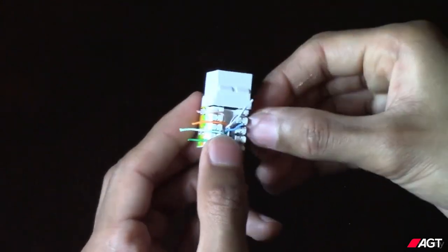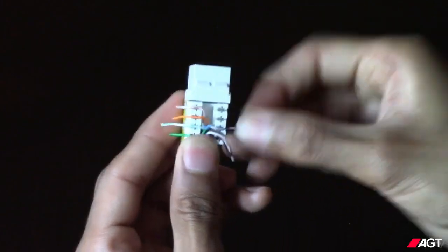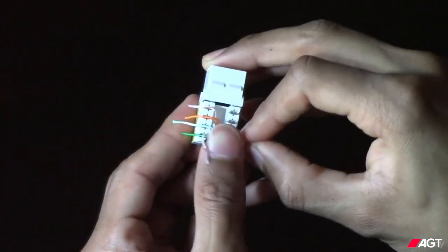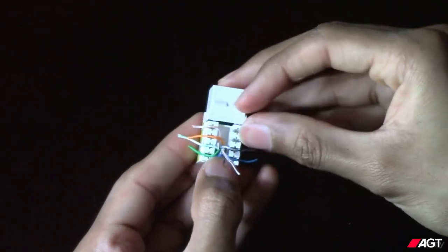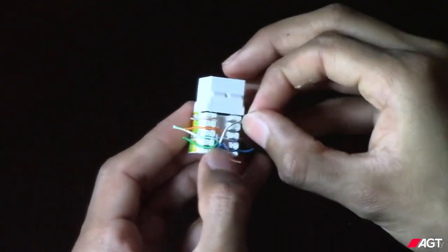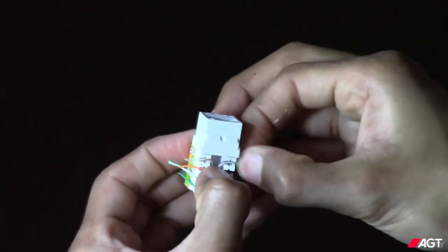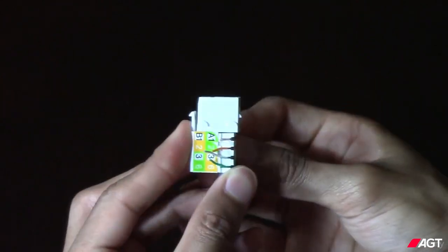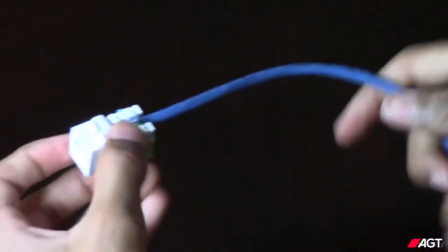Also, try to work with the wires. I just took off the top two wires to fit the bottom two first, just because the wires were getting a little too tangled near the end of the sheath. You'll see what I mean when you're actually doing this yourself. Just try to maneuver the wires so that you're not tangling them at the end of the cable. So now we have all our wires loosely secured to the jack. In the next video, we'll be using the punch down tool to secure our wires.